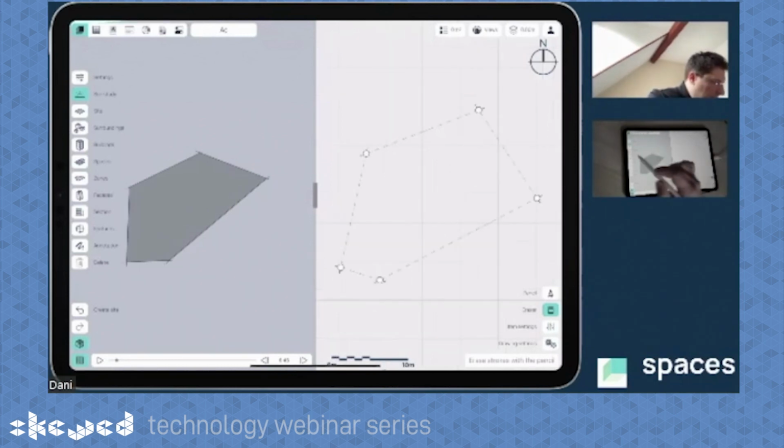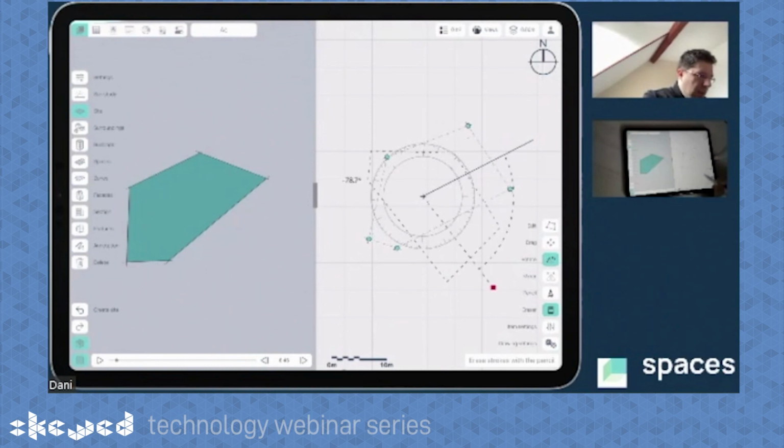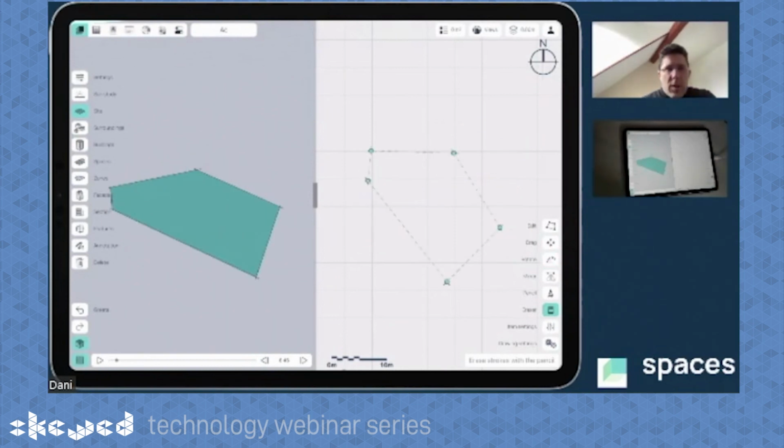So if I select, for example, this site, and it happens to be in a different orientation than in real time, you can still rotate it and position it to the place you like. We can also adjust the project north direction via the project settings. So if you want to flip it around to the left or the right, or even just an offset angle.